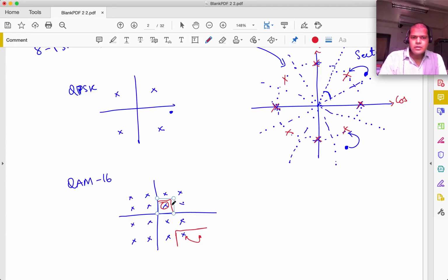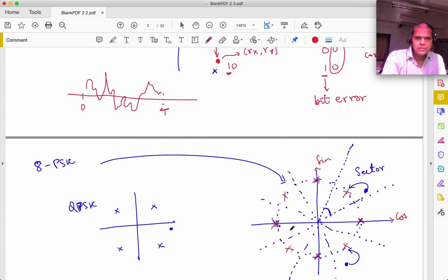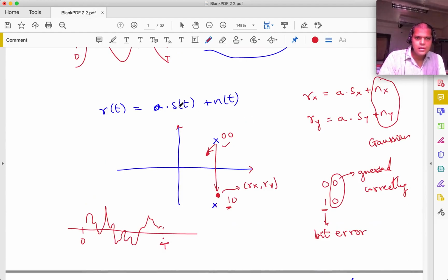So when are you going to use this versus 16 PSK, you might think, right? And so it really depends on the situation. You would have to look at the bit error rate in both cases. But also we have to look at other things. So the nice thing about PSK is that the amplitude doesn't come into the picture. So we said that your received signal is the transmitted signal multiplied by some attenuation. And attenuation is not going to affect PSK as much as QAM.